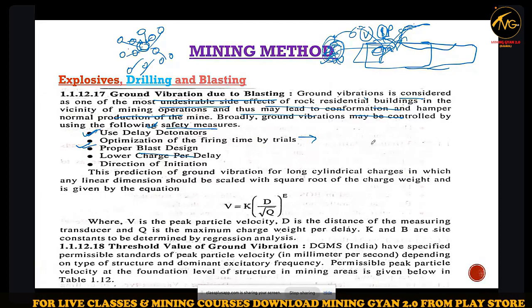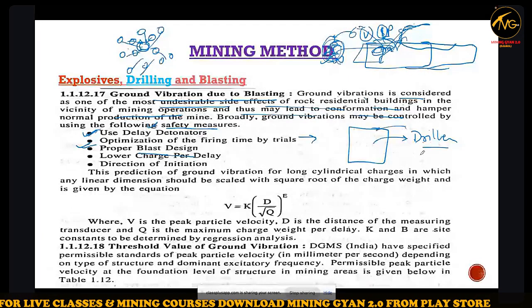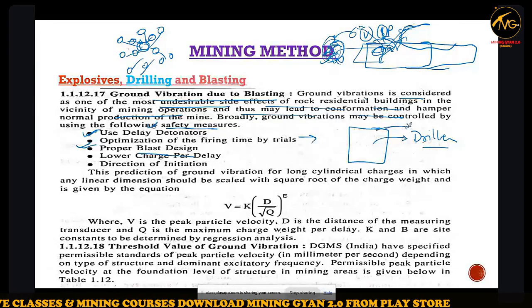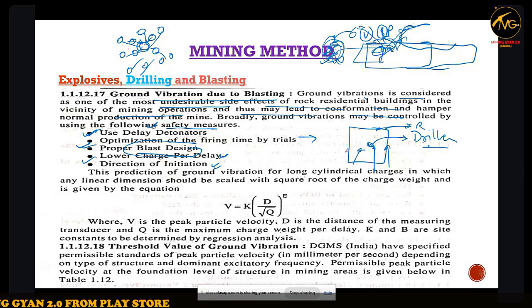Choose which type of blast drilling pattern is suitable for your strata, which type of rock. So the blast design is important. Charge per delay should be lower. Direction of initiation, from where you should start blasting. Threshold value of the ground vibration.